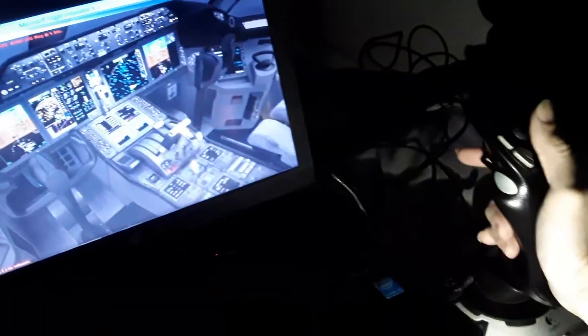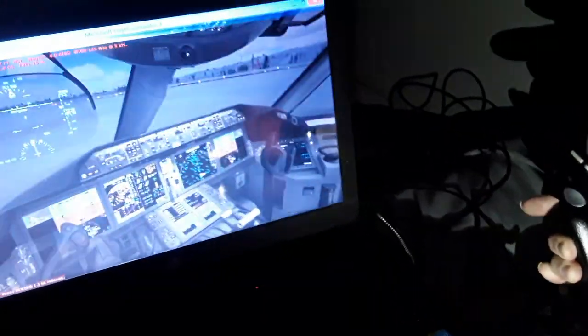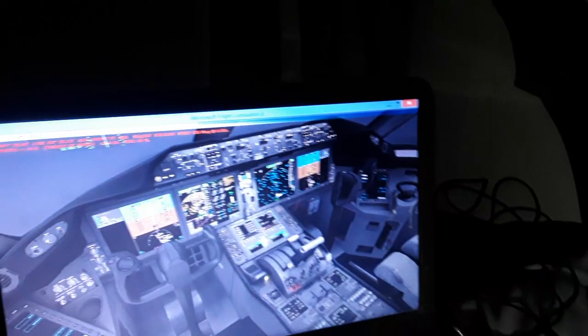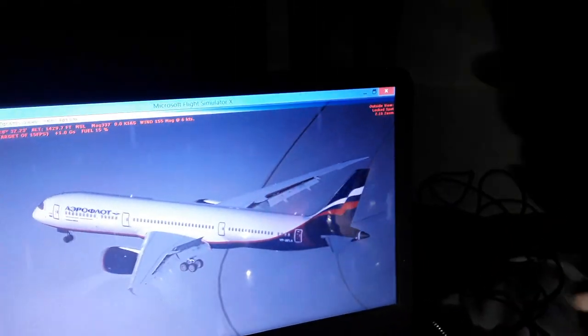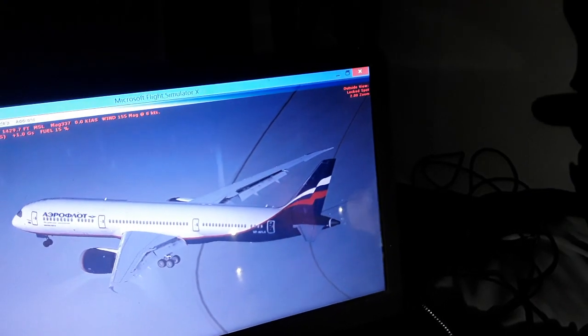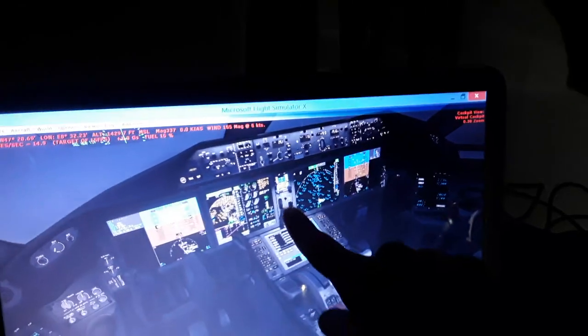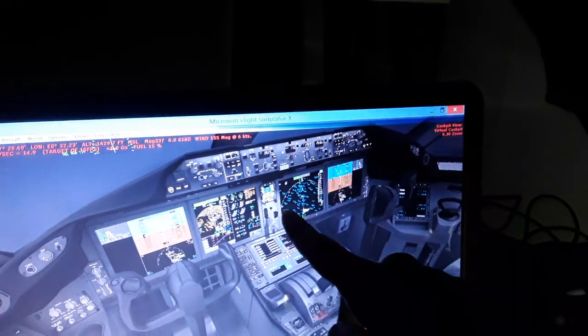Also the FADEC controls, as I told you, the outflow air from the 5th and the 9th stage, and the bypass air from the fan stage. So it admits pressurized air into the hydraulic fluid tanks. All these flight controls you see need hydraulic fluid, and receive pressurization from the engines when they work. So you see all the flight controls here moving, like the wings, the elevator, the tail, all need hydraulic pressure. Also the landing gear extends and retracts here.